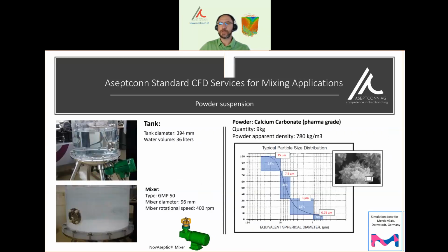Another standard service is the powder suspension option for studying the mixing of a non-dissolving powder into the main liquid. The main target of the study is to understand the powder behavior in relation with the main liquid and to perform an analysis of the homogeneity and mixing time. In this example, the application is the mixing of calcium carbonate pharma-grade powder.